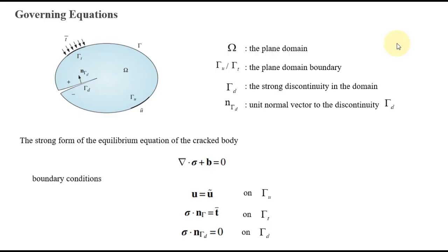I will be presenting the governing equation of the extended finite element method, particularly in the context of linear fracture mechanics. We begin by considering a cracked domain where discontinuities, such as cracks, are represented implicitly without the need to remesh the geometry.